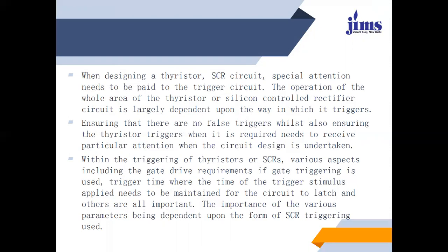We have a limited time period under which the SCR must be turned on in case of the AC supply. In the Indian case, we have the 50 hertz frequency. 50 hertz means the time period for the positive half cycle is 0.01 second. So within that period, the SCR must be turned on.